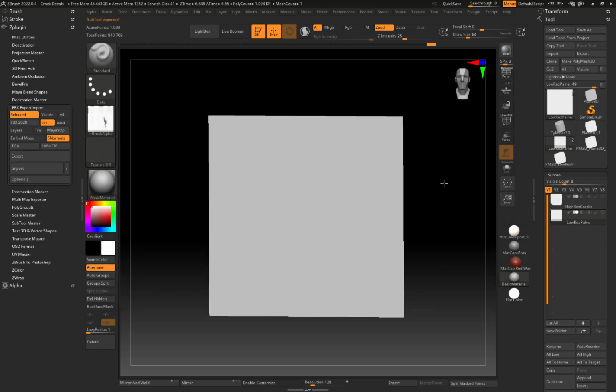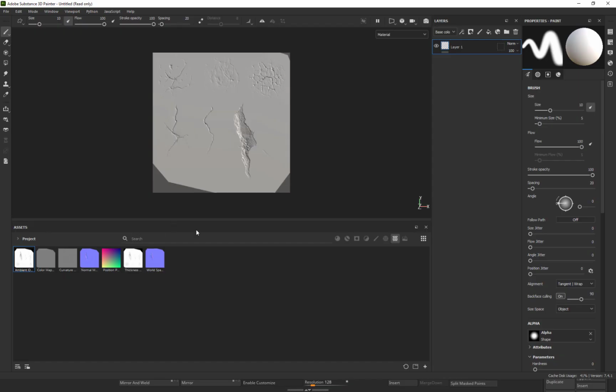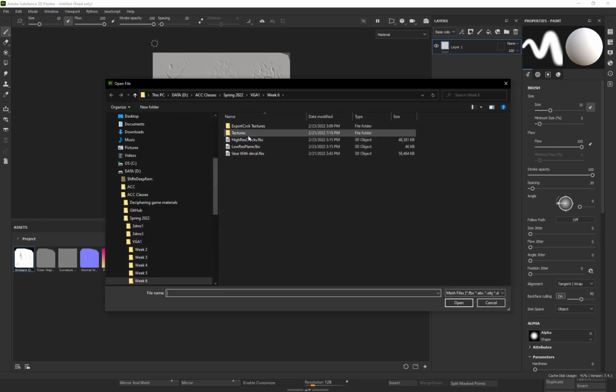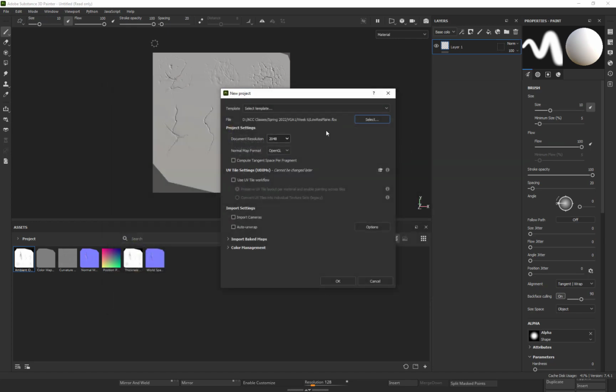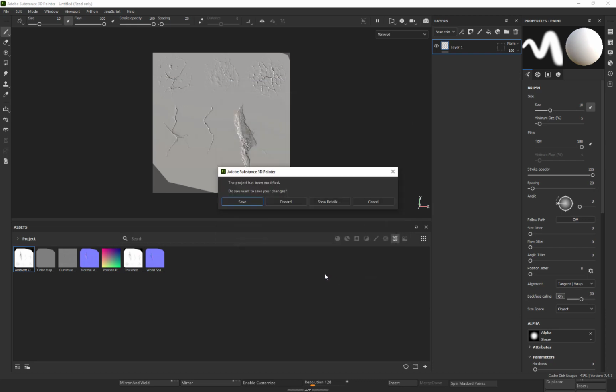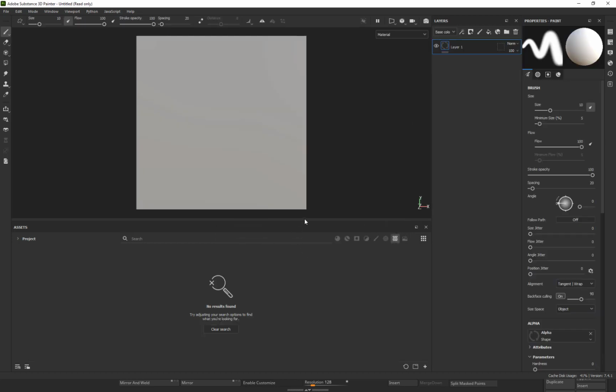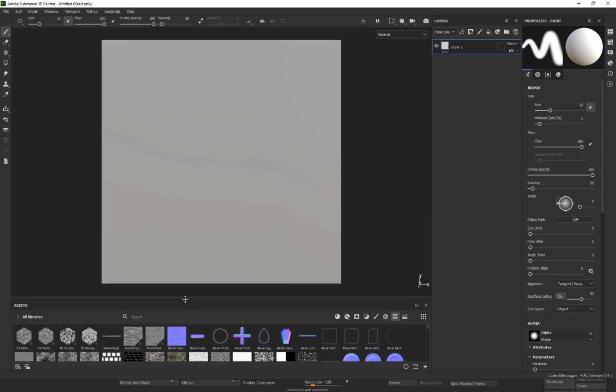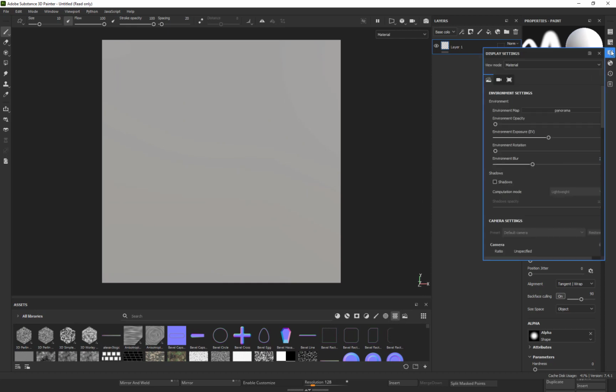And that was a little faster. Okay. So then I'm going to open up Substance Painter. And in Substance Painter, I already did it once, so we'll just start over. File, new, select image, and we'll take the low res plane. And as long as I named it, my life is easy. So I'll do that. No, discard what I worked on. Get rid of project information. I'll go to here. Then I'm going to bake it.